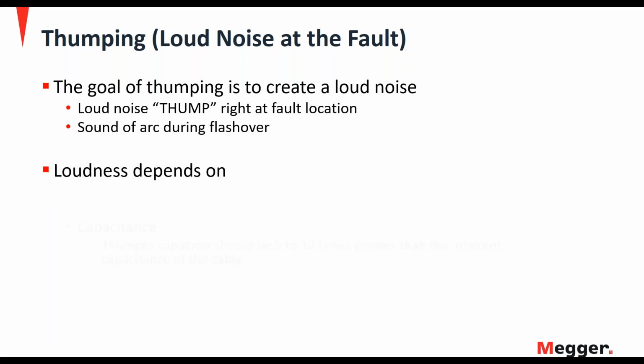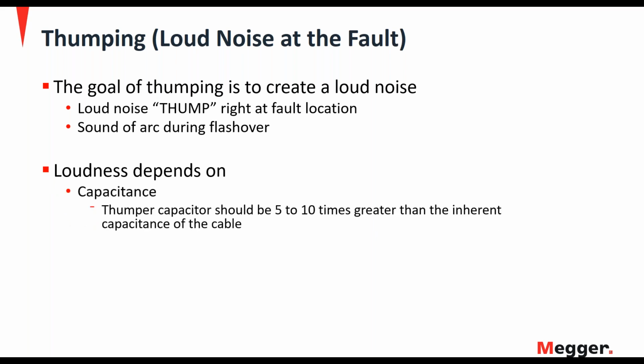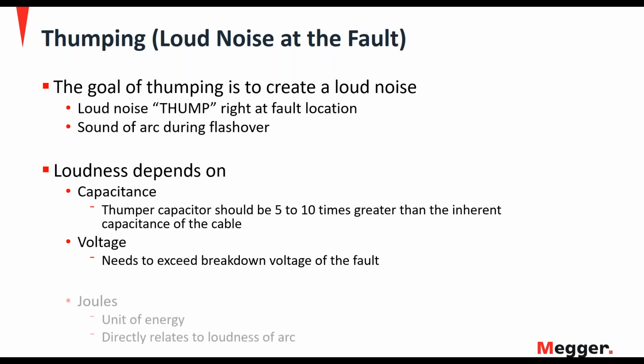And the loudness depends on two things. First, the capacitance that we use. Inside of the thumper is a capacitor. It should be roughly 5 to 10 times greater than the inherent capacitance of the cable. And second, we have voltage. We need to use enough voltage to exceed breakdown of the fault so that we can flash it over.